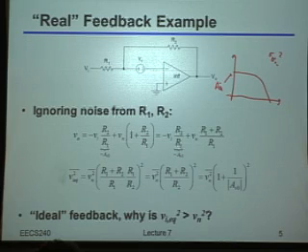That's the common technique people use, simply because the assumption is that you've made the bandwidth of the amplifier wide enough that the signal itself fits within the band of the amplifier. And so the gain you're applying to the signal itself is that DC gain. Now, you're absolutely correct. This is a hand-wavy approximation. So you have to be really careful when you start talking about integrated noise. The only proper thing to really look at is the signal-to-noise ratio after all the integrations have been evaluated. Otherwise, you're somewhat waving your hands.